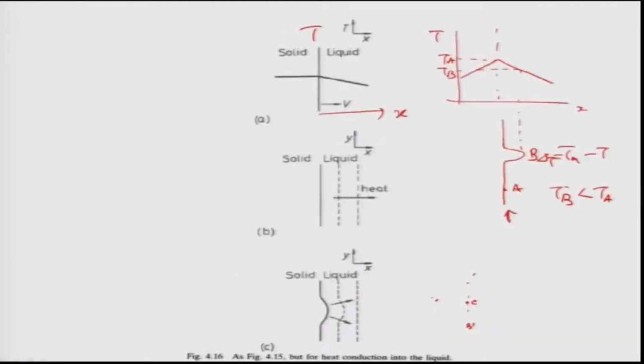It is very easy to form another protrusion. Let me draw it firstly. So what I have done is like this: I have drawn two protrusions and I have drawn two points B prime, and then I have drawn a point C; this is point A. As point C is getting undercooled more than the two B primes here, obviously A is at a high temperature, so the question of A does not arise. Just to show, I have drawn A. Because of this high undercooling at point C compared to point B prime, the protrusion will form like this and grow. It can go like that.